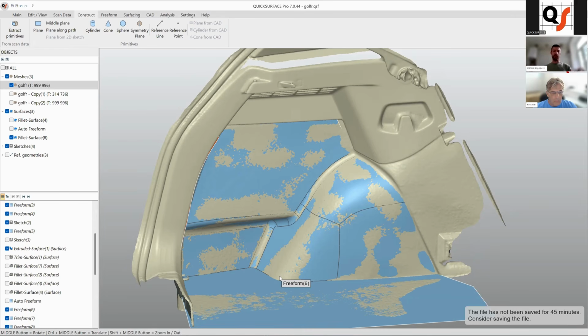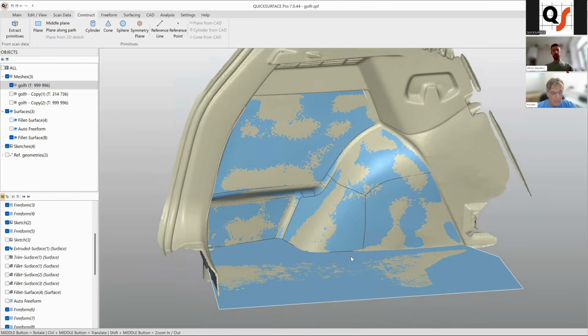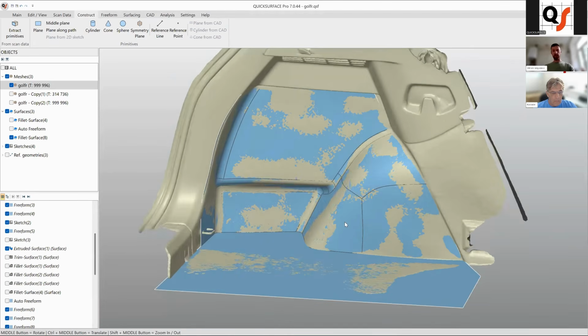And if your mesh has some roughness, definitely you will see the bad result there as ripples and things like that, and it will be difficult to handle them. So you would have to switch from like 20 quads to 5 quads on this side, and you would have to actually plan how to proceed with that. And it's not that easy, and it actually takes much more time if you are not an expert in subdivisional modeling.